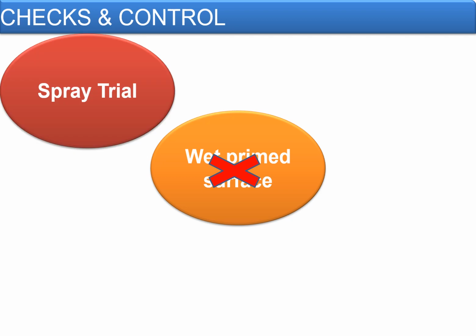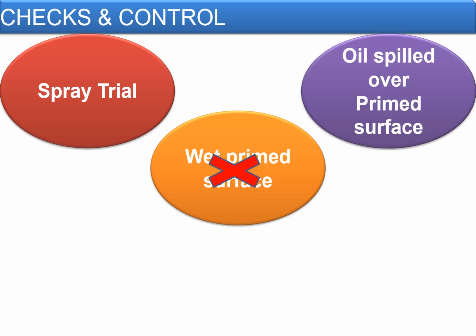Any unabsorbed material shall first be blotted with a light application of either sand or lime or any absorbing material. The idea is to absorb the excess material which is there on top of the HMA layer, and apply a fresh tack coat and then proceed with the new HMA layers.